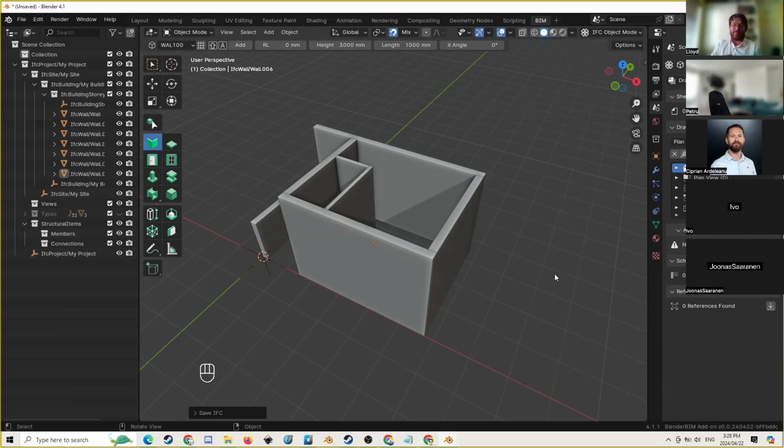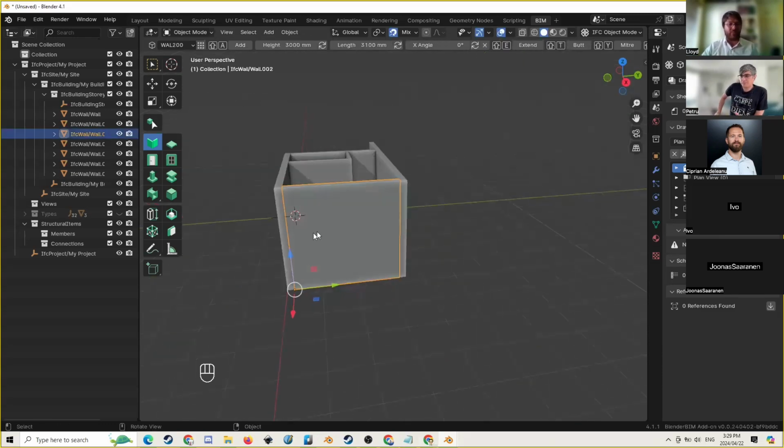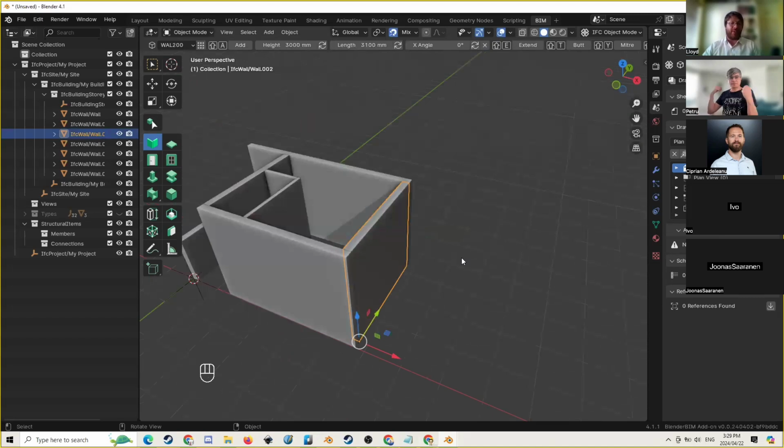And it attaches information like thermal performance, quantities, and attributes, like what the material of the door is. When it's attached inside of Blender BIM, you can take that information out. But inside of Blender, some of that information is there. Like we could probably get the area of this wall, but we wouldn't be able to get the volume out of it without an additional add-on. So Blender BIM does all of that in one go, essentially. So I think that is the answer to that question.